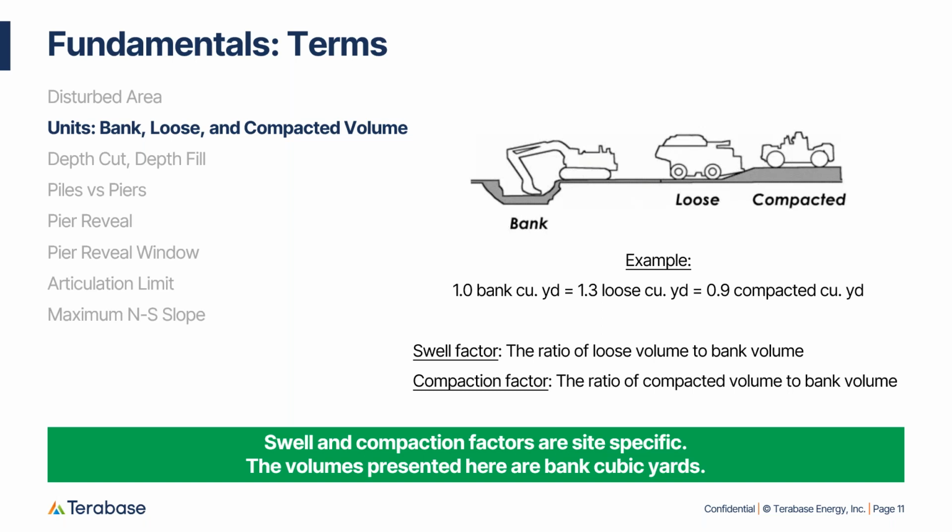So it's imperative to include these requests when you're scoping your geotechnical report. You ask the geotech for recommendations on what they think these might be, because it does have an impact on your cost. You can have swell factors of 1.6. That makes a big difference when you're trying to move that soil around the site. So we want to be clear that our software is estimating bank cubic yards, and we want to highlight that earthwork assessments can be nuanced when you're seeking balanced cut and fill.